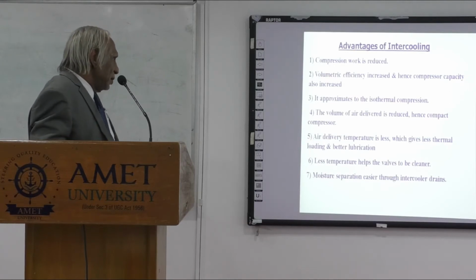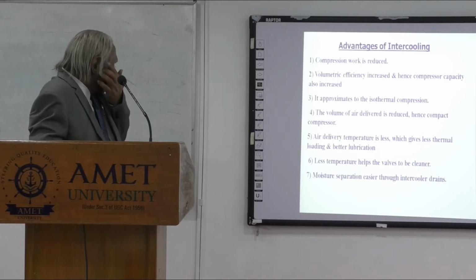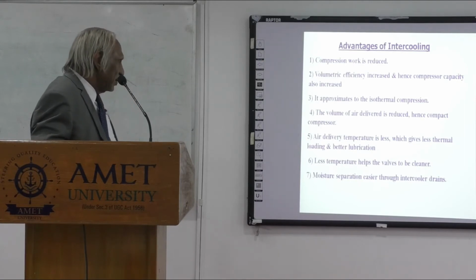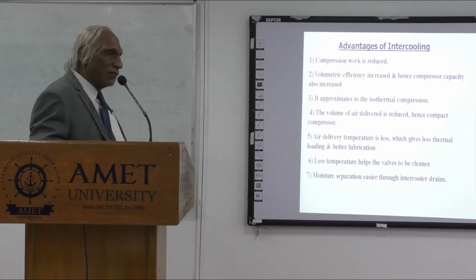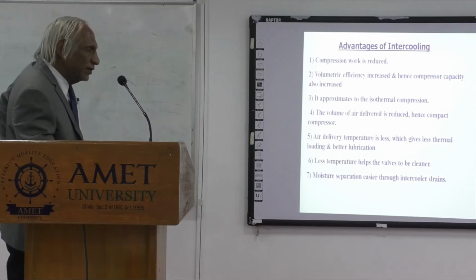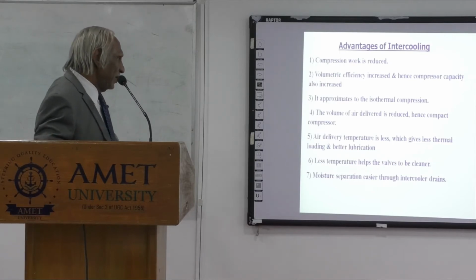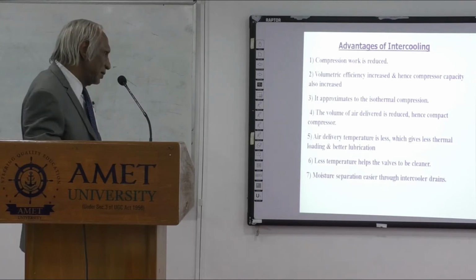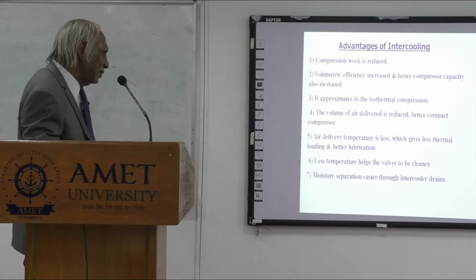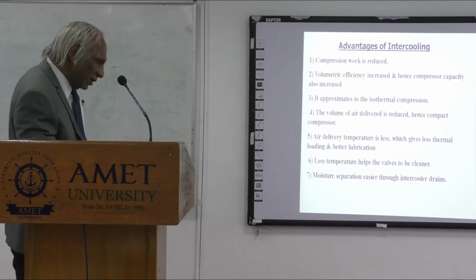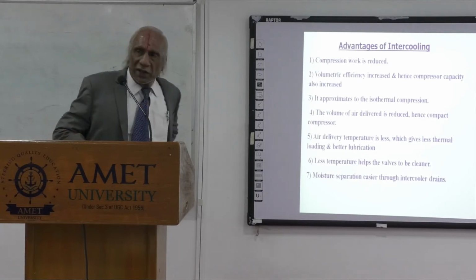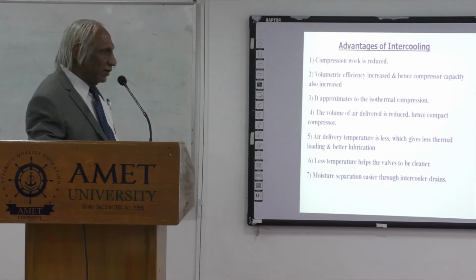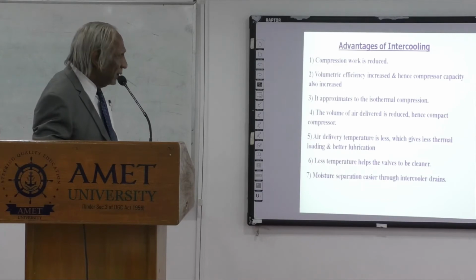The next thing is that because of the lower temperature, the operating valves, suction valve and discharge valve, will be cleaner. The amount of carbonization from lubricating oil will be much less. Moisture separation is easier through intercooler drains, because we all know that as the pressure increases, the saturation temperature also increases for the moisture.